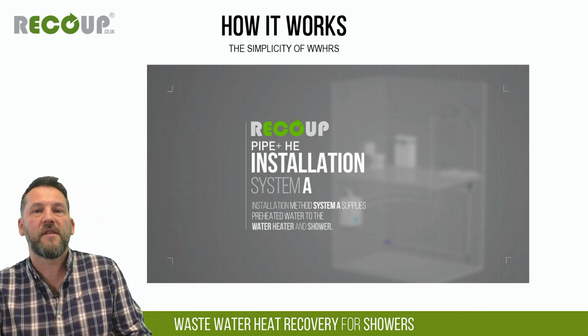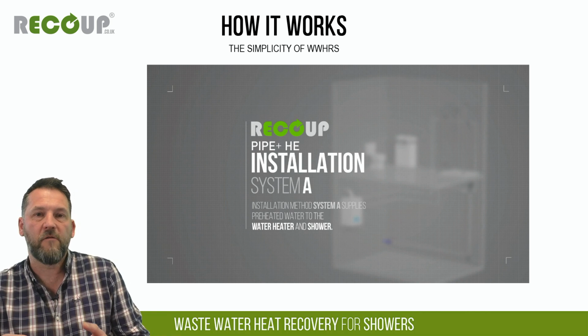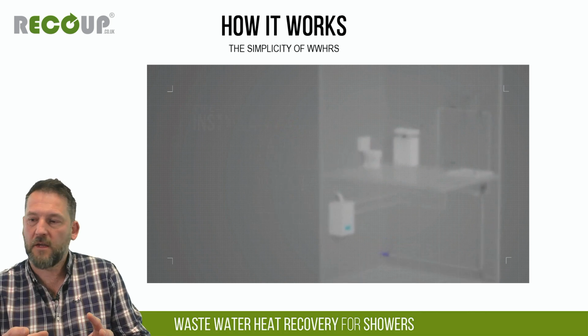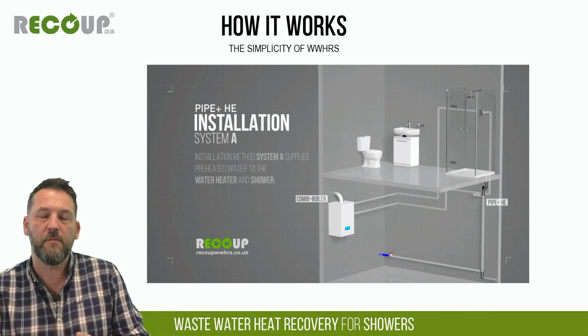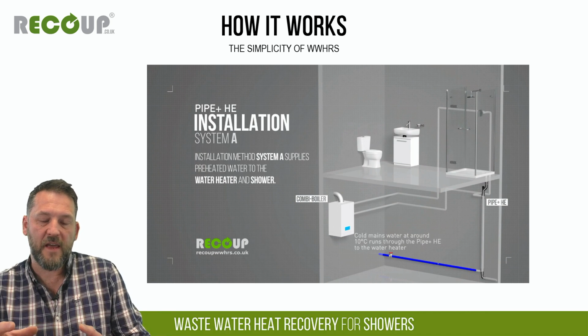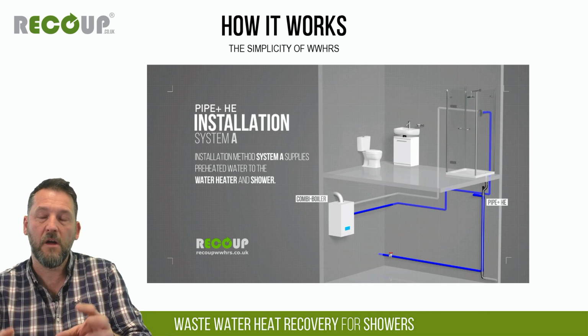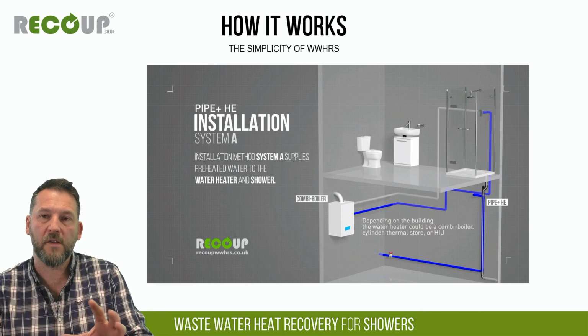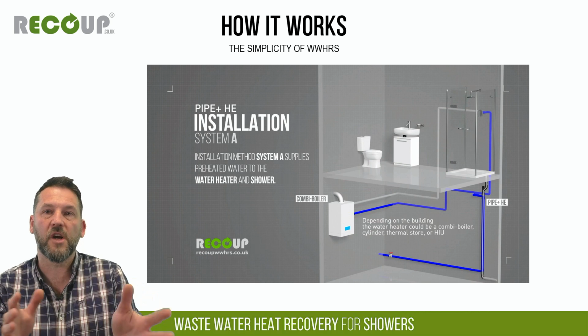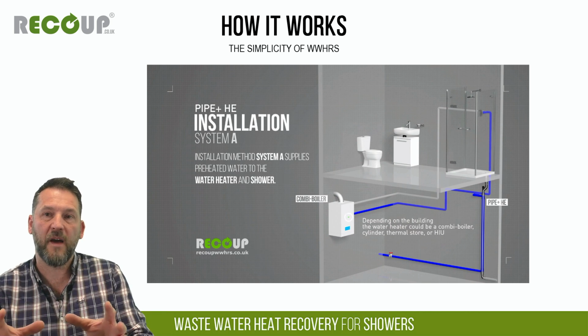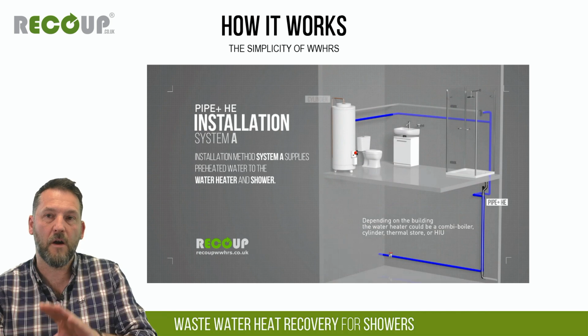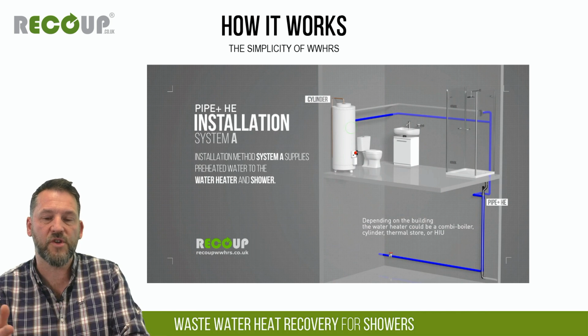So it's important to say at the outset that wastewater heat recovery requires a thermostatic shower mixer to be SAP compliant. The reason for that is a thermostatic mixer will allow for a fixed flow rate and a desired temperature regardless of what's going on in the background in terms of hot water and cold water temperatures. So the thermostatic mixer will adjust the ratio of hot to cold in the background to maintain fixed flow and fixed or desired temperature.